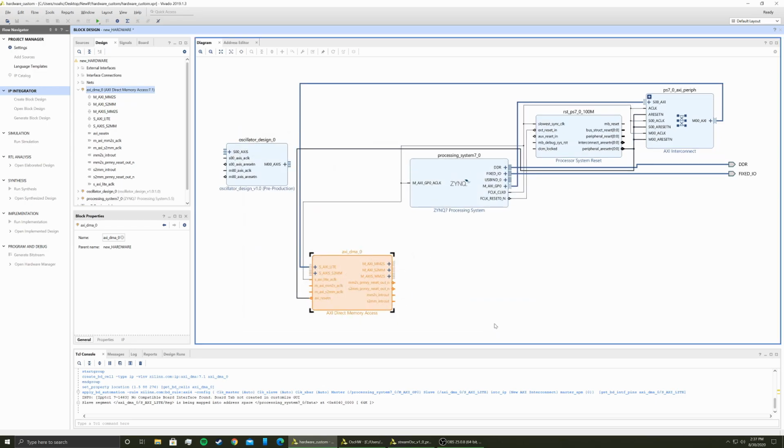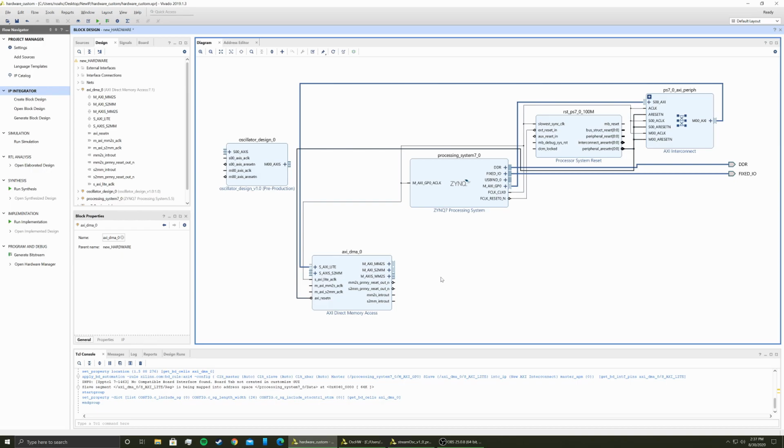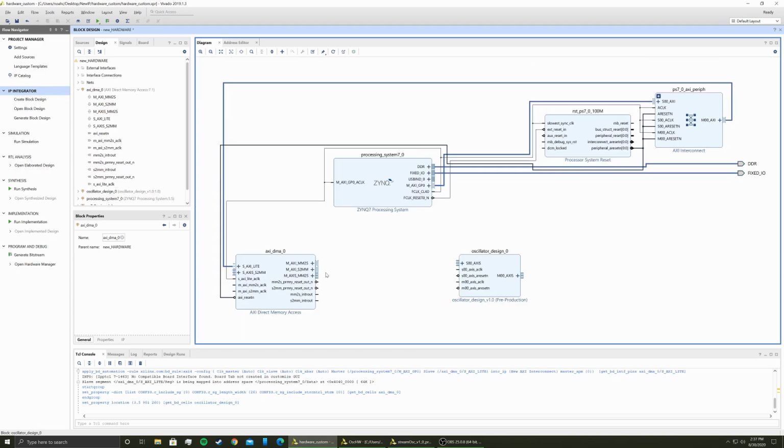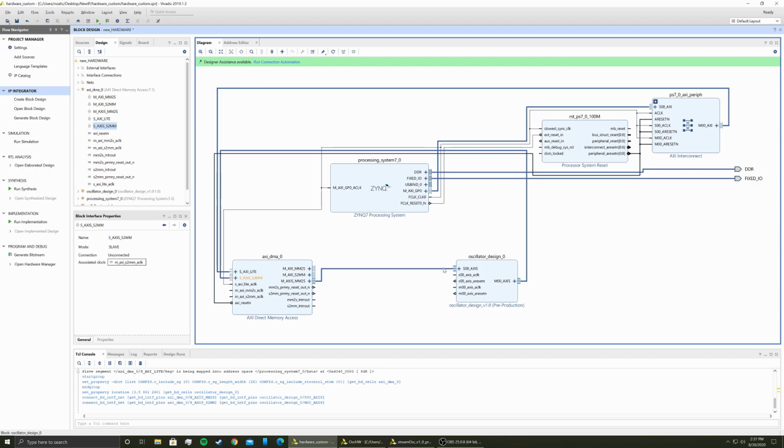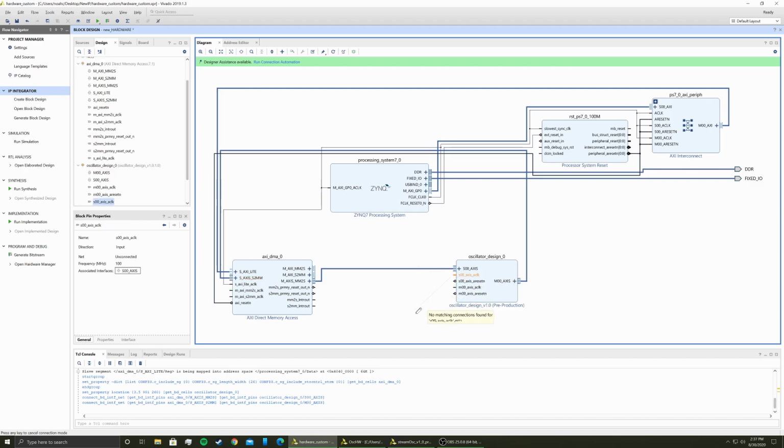So we're going to press OK here. And then one of the latter things in finishing up the connection design is connecting the ports of your IP design. So you're going to want to find the stream ports. These will be the AXI S ports labeled on the AXI DMA. Here we have a master AXI S port that goes from memory mapped to stream. We're going to connect this one over to the slave AXI port, and then as well we're going to be connecting the slave AXI S from stream to memory map. This will allow us to essentially gather our data from the master AXI stream port on our design. So we'll connect those. And then we will connect the clocks of our systems.